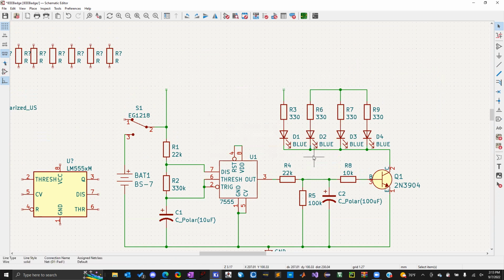When you're actually wiring it, let me go ahead and move some wires, and then I'll show you a cool fancy way to do it. To add the wires, you'd come to the end, you'd connect it. You'd click where you want to start, click where you want to end. Or if you're already at the starting point, just click W and it will automatically place it, and then you just click at the end you want. Then this has to connect up here. Another nice feature with KiCad: instead of connecting here to here, and then in between the resistor and the LED, and then the end to here, you can just click here and draw a line all the way through the components, and it'll place it on both ends for you. So you don't have to click multiple times. It saves a little bit more time.